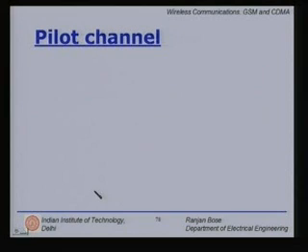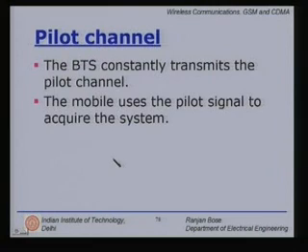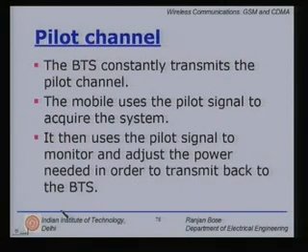What does the pilot channel do? The BTS, our base station, constantly transmits the pilot channel. The mobile uses the pilot signals to acquire the system. It then uses the pilot signal to monitor and adjust the power needed in order to transmit back to the base station. Please note that CDMA systems rely heavily on power control.